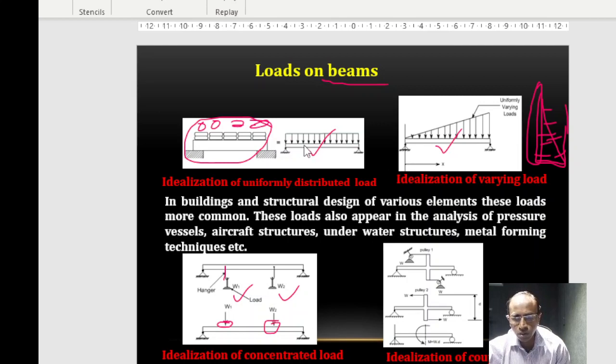And then when the load is uniformly spread out over a large distance, it is called uniformly distributed. Now sometimes two equal and opposite loads act separated by some distance, such as through a pulley here with a load applied here, and through another pulley. These weights keep moving, so you can increase the load here or there. This will create a kind of couple, or it's called a moment. So two equal and opposite loads acting at a specific distance create a couple, and that is represented this way.